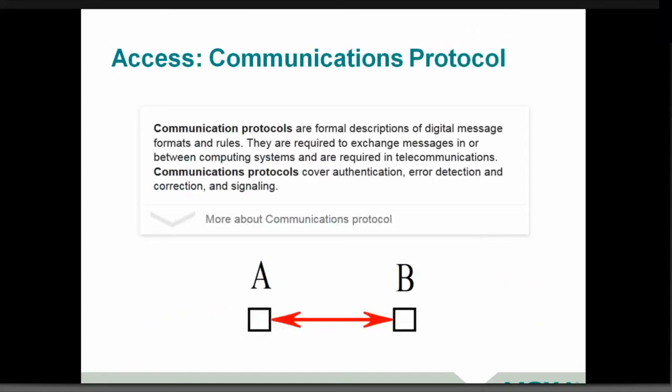Now, when we talk about bringing these types of sensors into a common technology like IP networking and specifically Wi-Fi, you need to understand first how to interface with a sensor, and second, how we're going to get that raw information, like a 0 to 10 volt signal, into something that maybe your SCADA system can understand, whether you're using something like Wonderware or any of the dozens of other great packages out there.